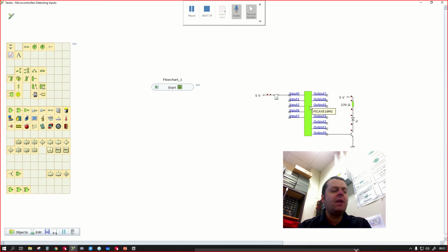And that was why I was saying, if you use a stop bubble, if you've got a set of sequential code that runs and then stops, the only way the microcontroller will ever do that code again is if you take the power away and turn it back on again. As soon as you turn it back on, it'll immediately start executing that code again.